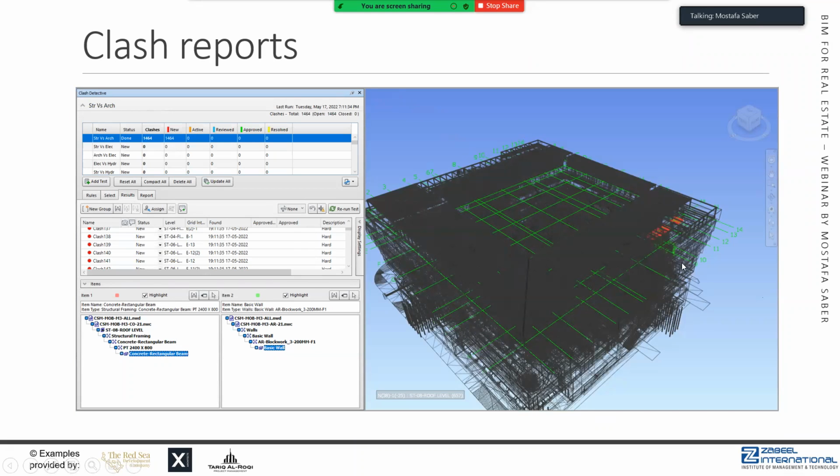about this project, we also created clash reports on site by the contractor that started studying the model and submitting his drawings to us in terms of NWD files, that is Navisworks native files, and drawings as well. So instead of reviewing a set of shop drawings by the contractor, you'll be able to review the shop drawings with the relevant models and clashes that are already there. And this means the consultant will be able to take better decisions and make sure that things are already coordinated before approving any shop drawing.